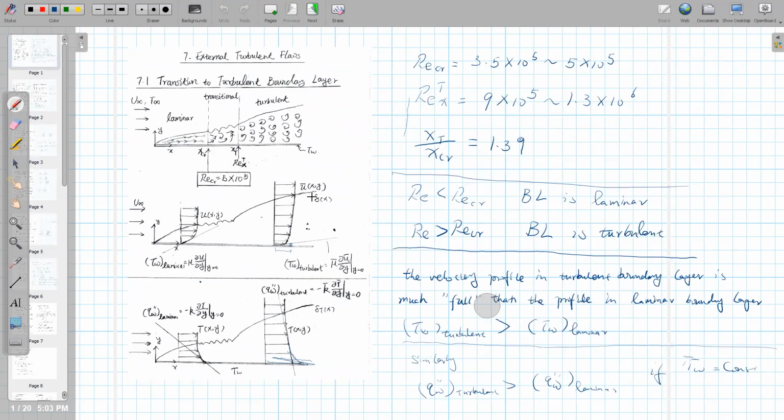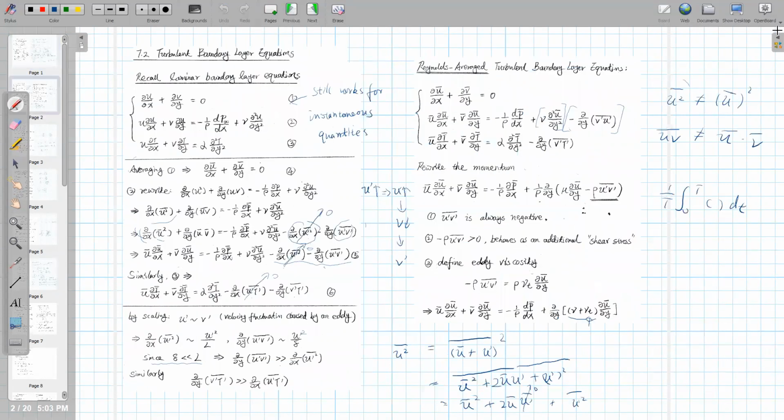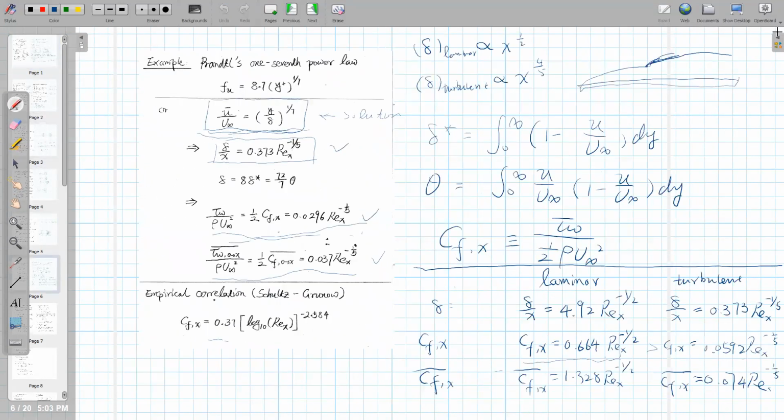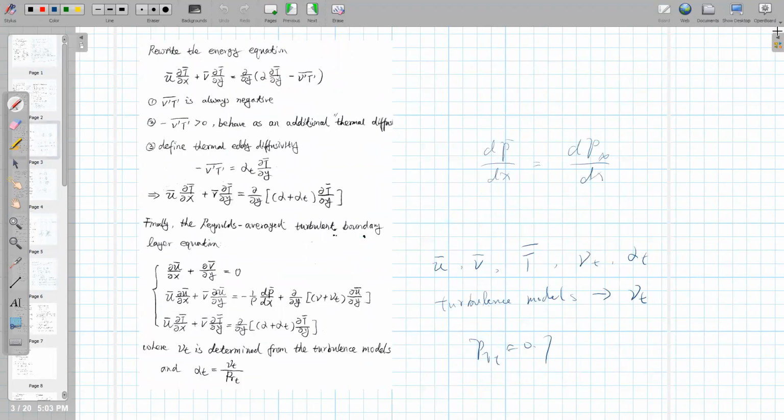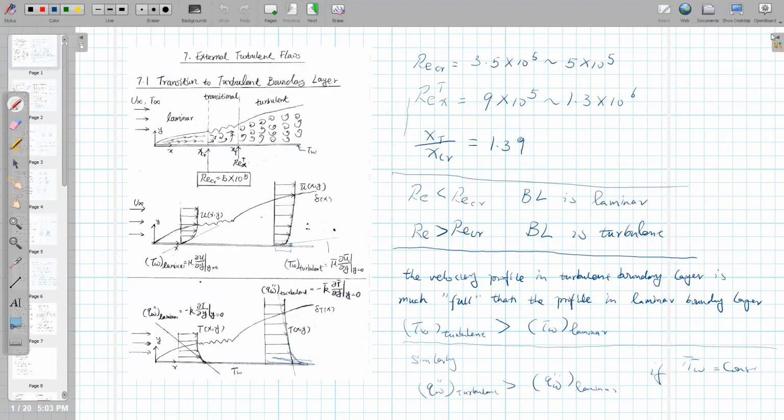Actually, the turbulence will try to increase the viscous force, and that's why the boundary layer thickness increases. My fault. All right, I know that it is a little bit confusing because of my mistakes, but I just want to emphasize that the effect of turbulence will actually enhance the wall friction.